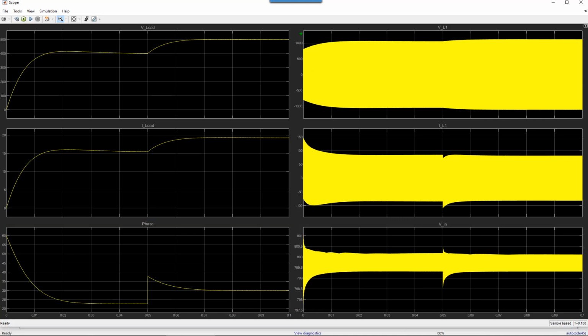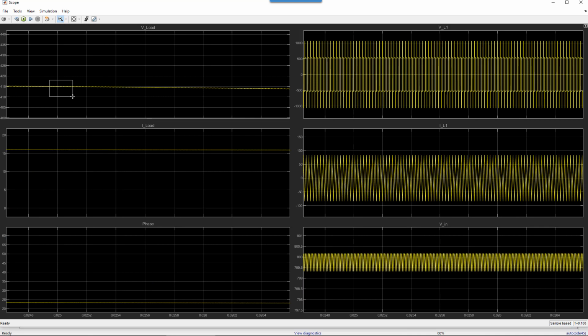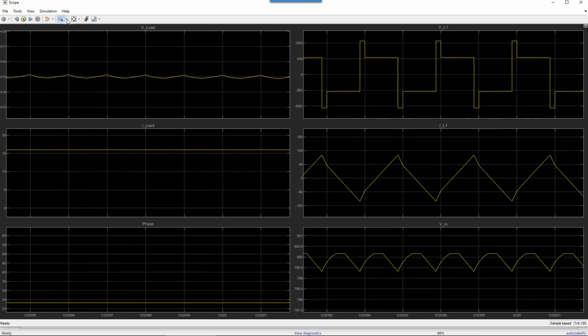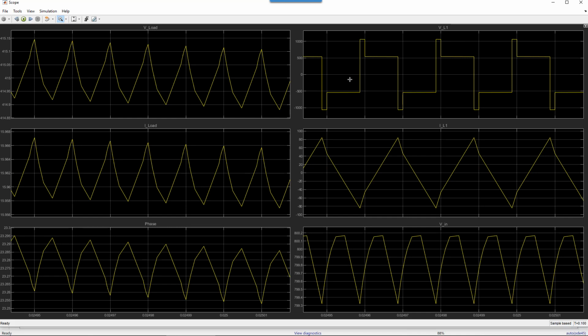And then I've got some other signals that I was looking at as far as the input voltage and the current and voltage across the inductor. It is nice because if you zoom in on a couple of these, you do get to quite easily see how a DAB inductor actually works. And so you can see you essentially have control over the voltage across the inductor. And so you can apply a higher voltage and a lower voltage across it in both directions.